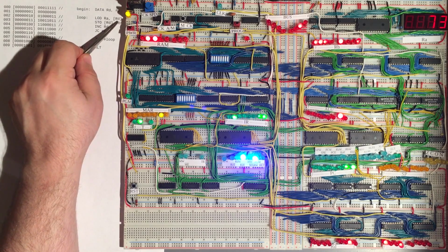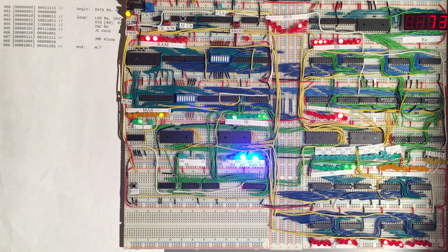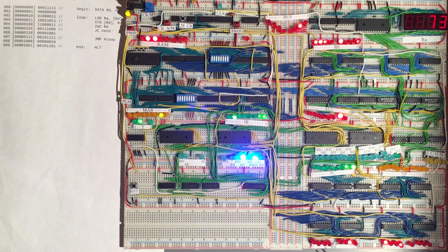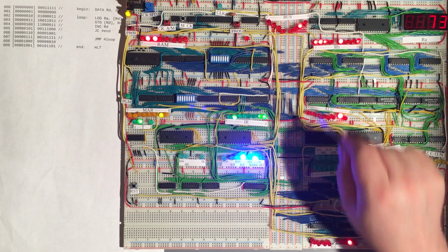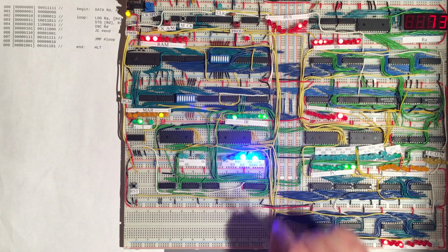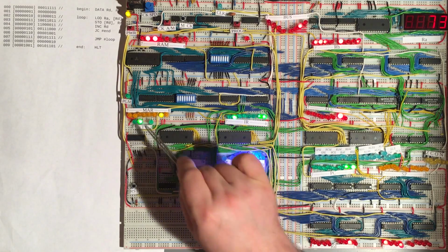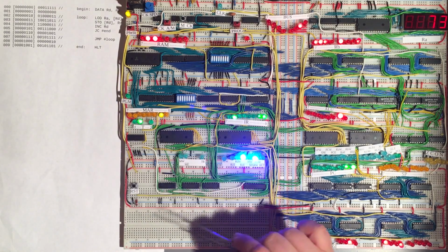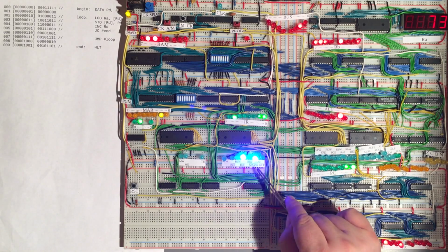So since we want to access data at the address which is currently in the D register, the first thing we need to do is to get the contents of the D register into the memory address register, so we can point there. And so what we need to do is enable the D register onto the bus, which is what this control signal achieves. And then subsequently we need to write that into the memory address register, which will happen on the next rising clock edge. And so for time t2, the microcode for this load instruction needs to assert these two signals.